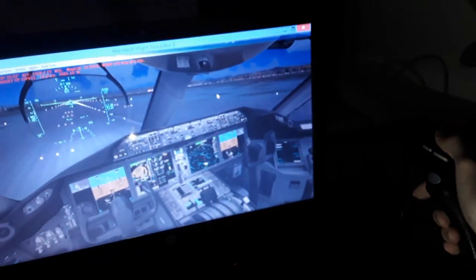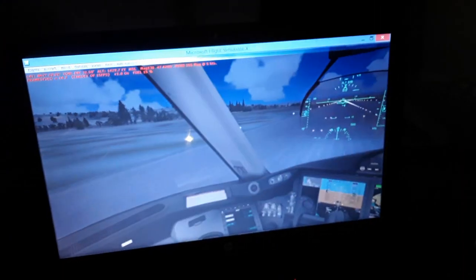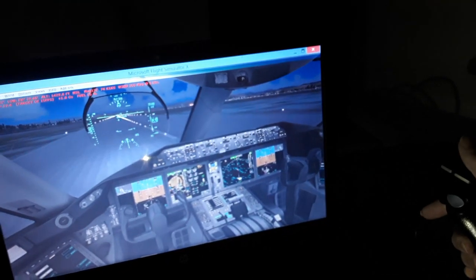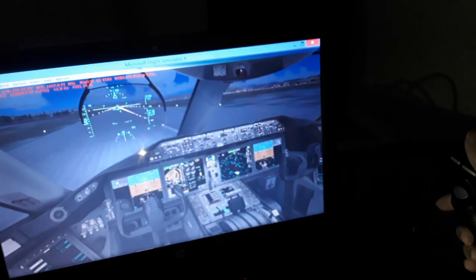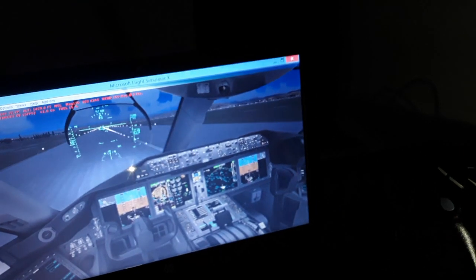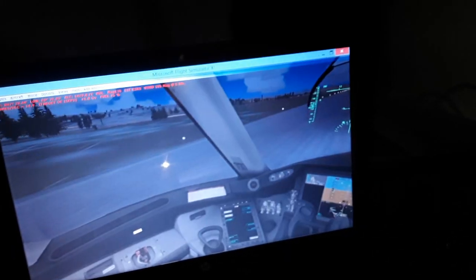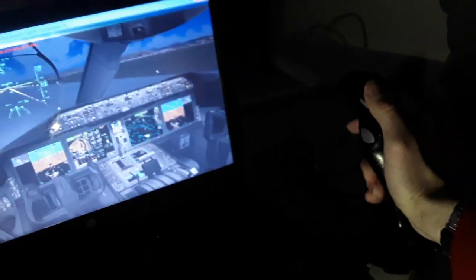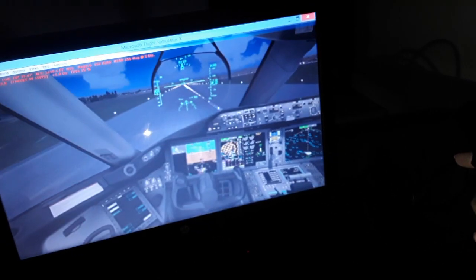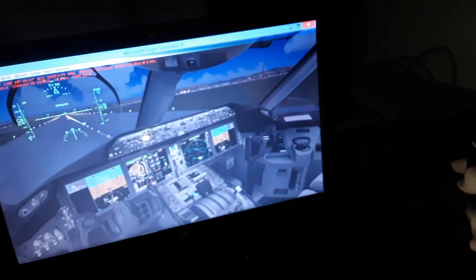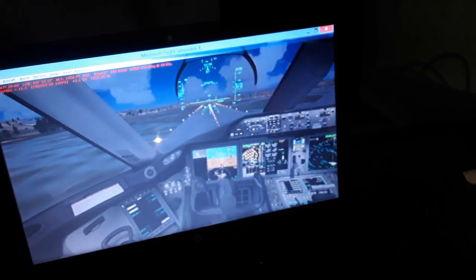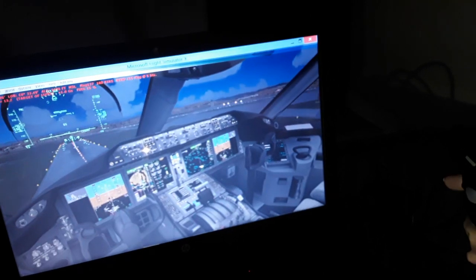For takeoff, and we push the side stick down until 80 knots. We align with the rudder pedals. So we have 80, 90 knots, 100, 110, 120, V1. We pitch up 9 degrees for rotation slightly. So we have V1, we rotate, V2, and we climb, as you can see.